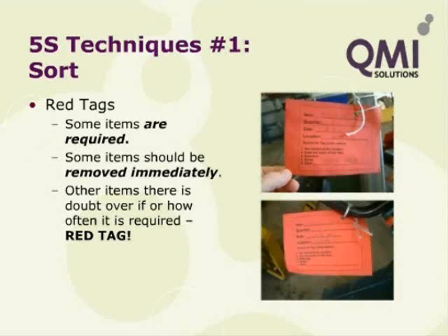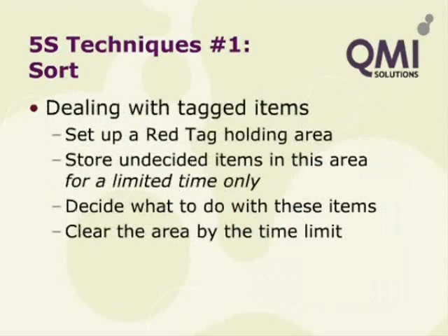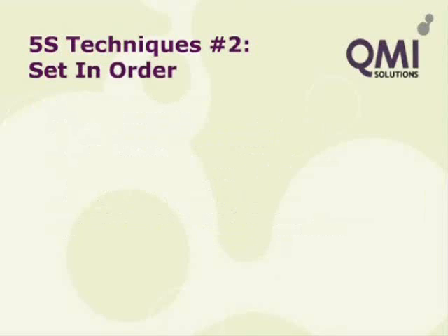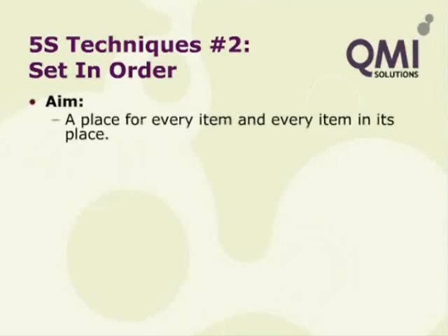The first step to introducing 5S is sort. In this step, seek to remove every item from a work area that is not required for the current operation of that work area. Consider both production items such as stock and service items such as tools and equipment. If an item is required in a work area, how many or how much of that item is required?